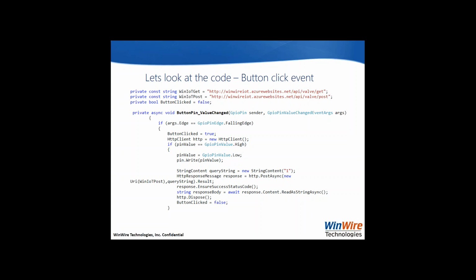And when this event is fired, we are writing some code for what we want to do in this particular scenario. Now we are checking the GPIO pin. This is important. GPIO pin is more a Windows 10 IoT Core or a board specific thing that you need to learn before you actually start writing code for Windows 10 IoT Core. Depending on the board that you have chosen, you have to select some pins on which you're going to work. Say for example, if I have to turn the voltage on or off, I choose a particular pin on Raspberry Pi that makes the connection so that the voltage is turned on or off. So you have to choose pins depending on your requirement and your needs, and then you have to write programs against those pins.